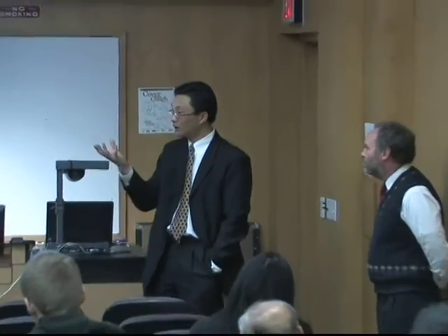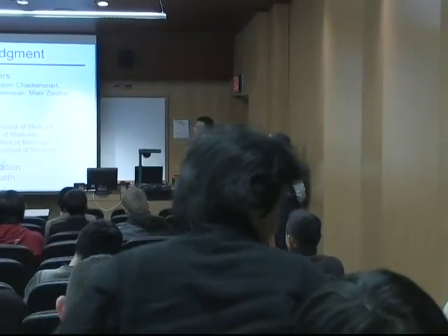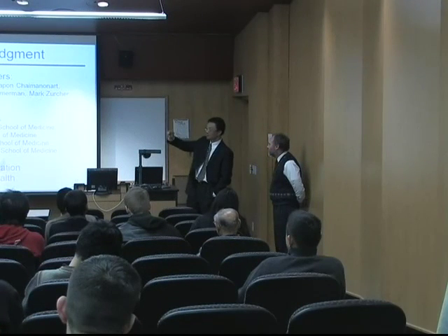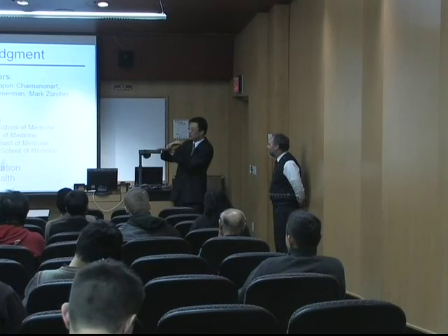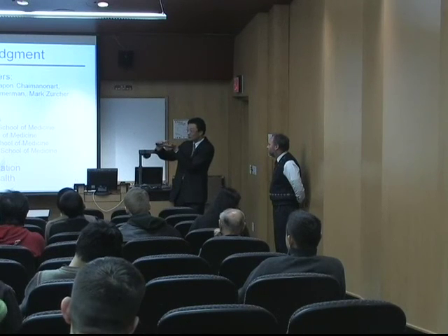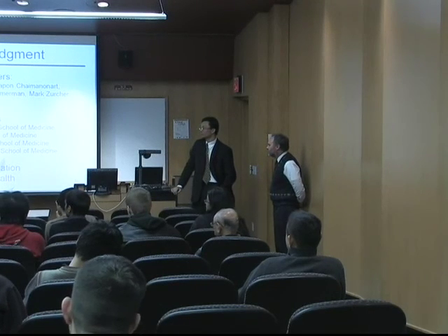Oh yeah, if you look at the implant picture, underneath the artery there is a tissue, but what's between the tissue and the artery is that substrate containing the MEMS IC modules and also containing the RF harmonic coil and other discrete components. On top of it is another piece, a flat silicone material, capped on top, with a thin stainless steel sheet encapsulated in the top cap to isolate the coupling. Yeah, I was just curious, is there anything holding all the electronics?